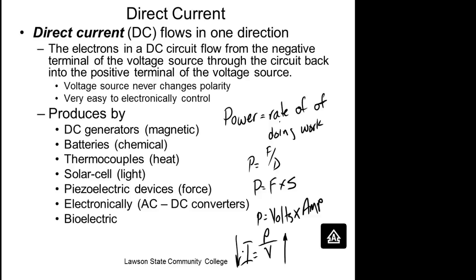Now the problem is the amount of voltage drop we get is equal to I times R, and everything has some type of opposition. A piece of wire has opposition. How much voltage we drop depends on the resistance times the current. So if I make the current extremely low, my wires are not going to drop much voltage.